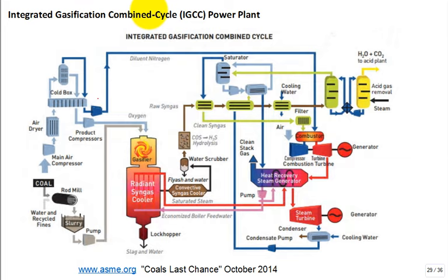You bring in coal. Where is our coal input? Okay? Somewhere. And you somehow make, with oxygen, some gas. The gas then goes and is burned like a natural gas and passed through a turbine. Right here is a combustor, and right here it goes out, hot gases through the combustor, natural gas. Air comes in, it's compressed, you have some fuel coming in. This is synthetic gas, syngas, cleaned up syngas. That comes from this coal stream like that.